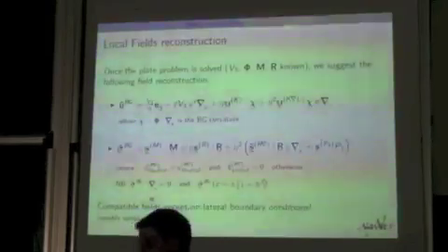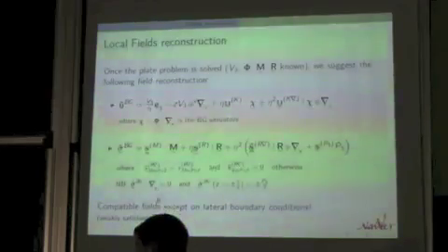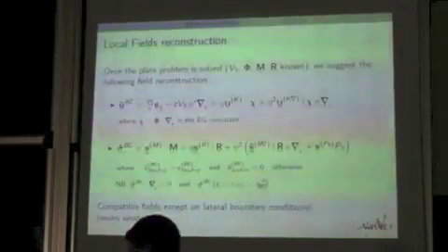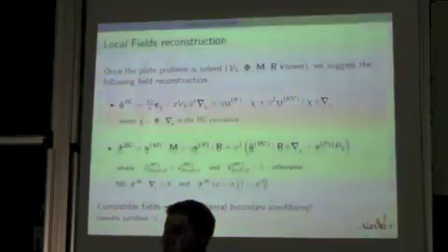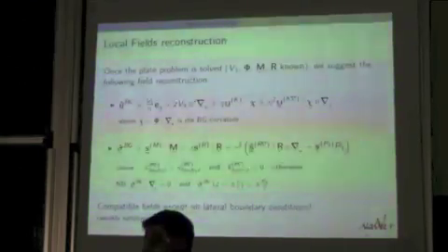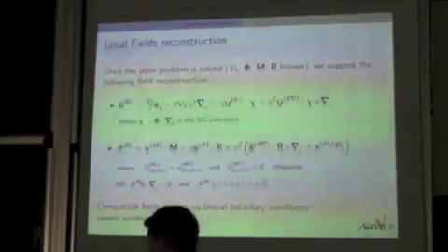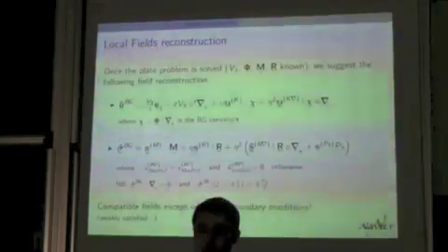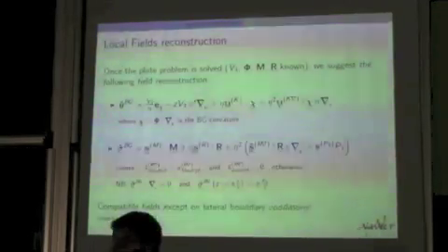Okay, I will go into details into that, but you satisfy the divergence equation, the equilibrium, and the stress boundary on the upper and lower face of the plate. Okay, this is very peculiar to plate models, to this situation. If you do this with a 3D periodic medium, you won't have a balanced, equilibrated stress field. Okay. So those fields are compatible, but this is very classical when you perform perturbation equations. They are compatible except on the lateral boundary of the plate, and these boundary conditions are weakly satisfied.